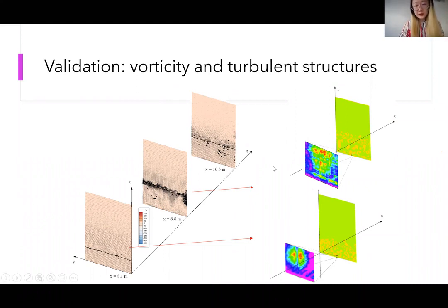So here on the left-hand side are the numerical results. The color of the slices are actually the vorticities, and as you can see, they're pretty consistent colors. Throughout the numerical domain, you get vorticity that is less than 100 or minus 100. So the magnitude of vorticity around the main flow direction is actually within plus or minus 100. And the black arrows are actually the velocity fields.